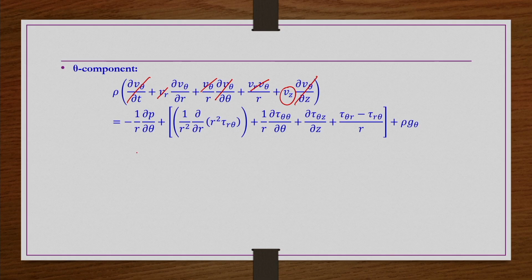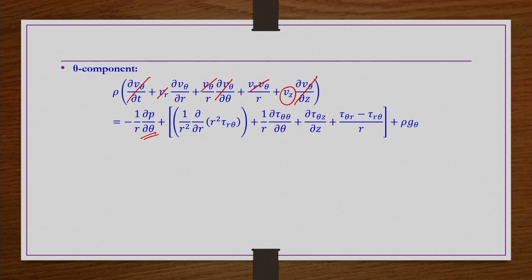right. So, the symmetry boundary conditions also in general are only for flow conditions, not for the scalars, temperature profile, pressure profile. We cannot generalize. Okay. So, let us keep it as it is.